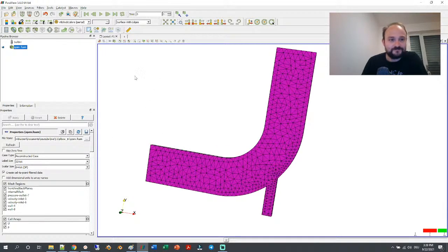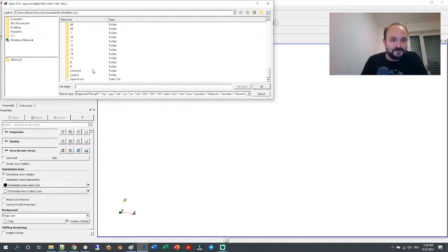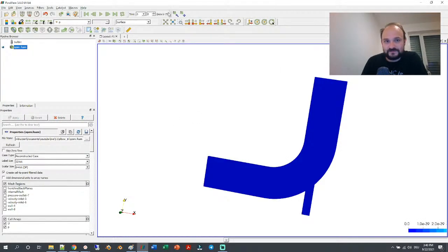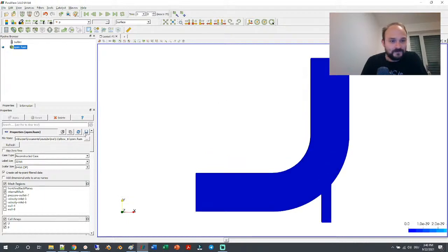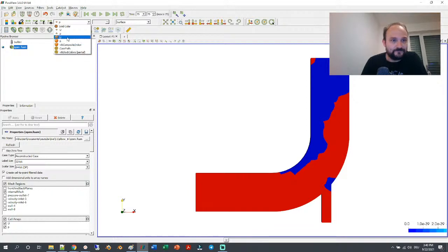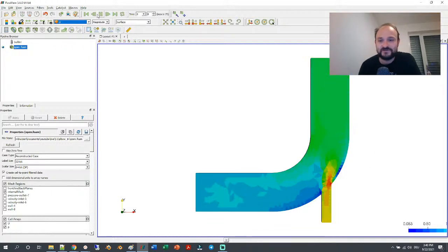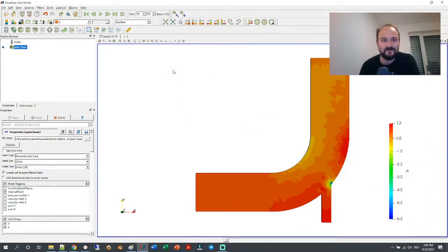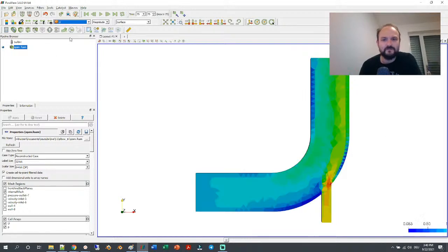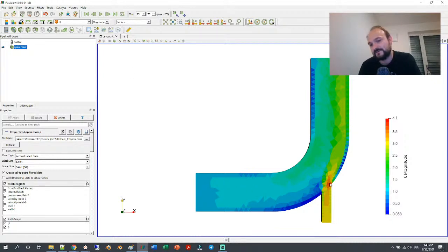And now we can just go into ParaView and refresh the simulation results. No, it's better to just reload it. Sometimes this works, sometimes it doesn't. Okay, now we have 75 simulation results here. And now, if I go to the very end and show you the velocity, so these are the simulation results. You can play it in ParaView if you want. You can also visualize the pressure. Here in this case, the pressure doesn't tell a lot. The velocity is more important. So what you can see is that this low velocity fluid mixes with the high velocity fluid, and then here you have a stream of higher velocity, here lower velocity, and here you can see the mesh, which is bad, and in the next live stream I will show you how the results will improve with a quad mesh.